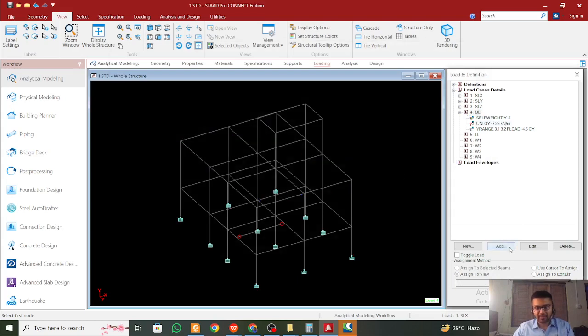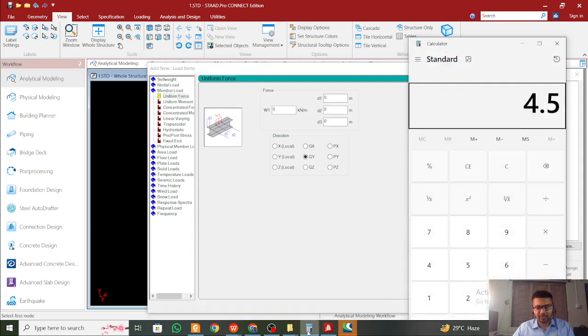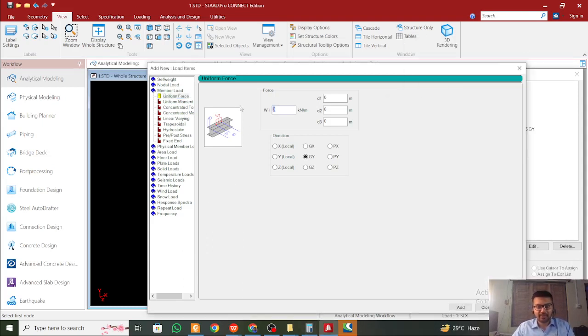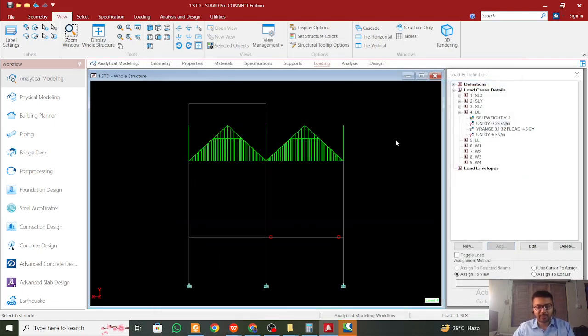I can add another load for the parapet wall as well. Member load for the parapet wall, we calculate, let's take 1 meter height, 20 unit weight of brick, and let's take 0.25, like full 10-inch walls for the parapet for safety, 5. So you have this minus 5 for the parapet, which will add, close. So first of all, 7.25 is in this floor.